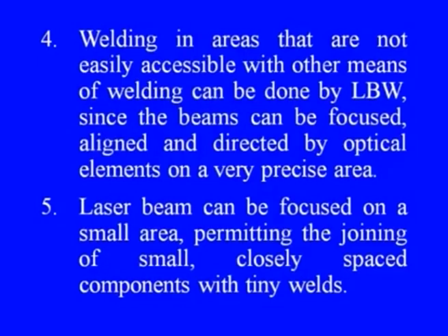Welding in areas that are not easily accessible with other means of welding can be done by laser beam welding, since the beams can be focused, aligned and directed by optical elements onto a very precise area. We have spoken about this in the case of electron beam welding as well.